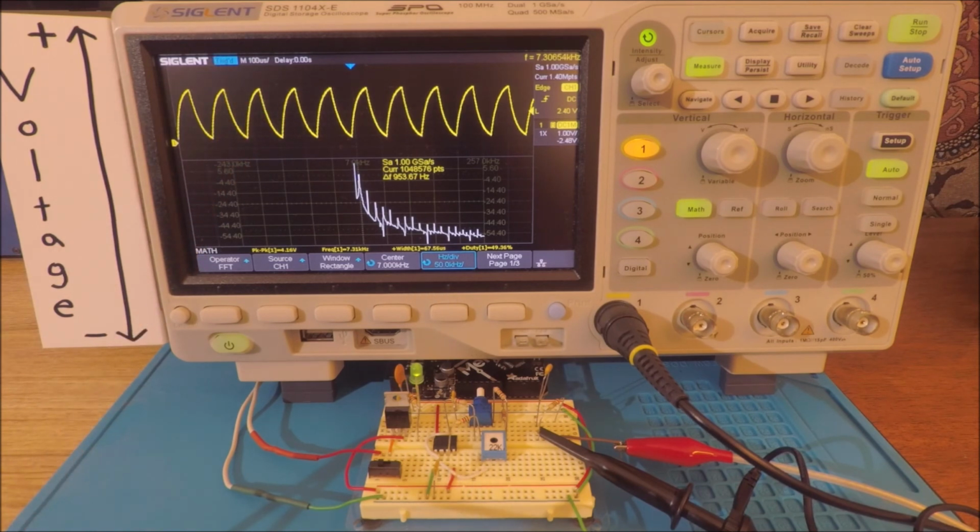As well, in the frequency domain, although we can see that the fundamental portion of the Fourier summation still exists, the higher order harmonics have been reduced. That's the low pass filtering in effect. Mathematically, we can explain this because the suppression of those higher order harmonics in the frequency domain are reducing the ability for the time domain signal to reproduce a nice rising and falling edge.